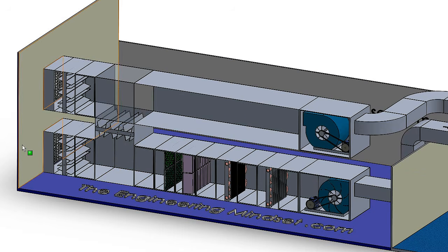Obviously there will be some fresh air. It's usually about 10% of all the air going around the system has to be fresh, but there will be some set points in the BMS, the building management system, which will control all that, and the controls experts will set that all up. But we will look at some real examples of this, not in this video. In this one, obviously we're just covering what's happening inside the AHU.